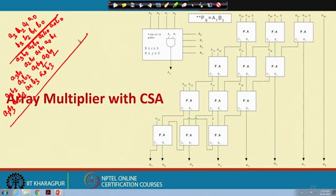Okay. Now, you see that for this position there is no addition operation, right, but for these two bits, this is 1 bit and this is 1 bit. So, for these 2 bits, if I want to add, I need one half adder. Whenever I do this half adder operation, the carry will be generated and propagated to the next level. That means if I consider this as carry 1, then that will come over here.